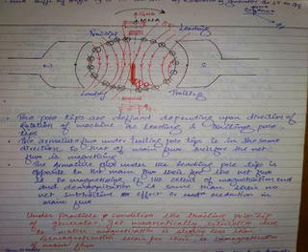In the same manner, when the pole is saturated, if you want to increase the flux in one pole half, it is reluctant to the increase, but there is no problem with a decrease. Is the point clear? For a decrease in flux, there is no problem with saturation. So the decrease will be there, but the same amount of increase will not. So due to saturation of the trailing pole tips in a generator, due to saturation of one of the pole halves, there will be a slight demagnetization.